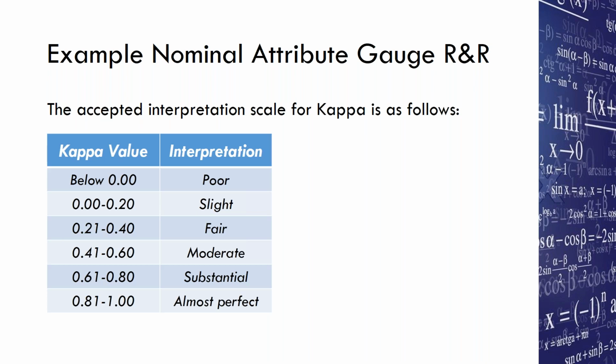But we had a supplier that had approached us saying that they had installed a particular rubber bumper in one of our latches upside down. And that was causing the latch not to function properly. So we had a number of vehicles that were parked in the lot that needed to be inspected. So we set up a gauge that the supplier provided us where we could do an assessment of whether that rubber bumper was installed right side up or upside down.